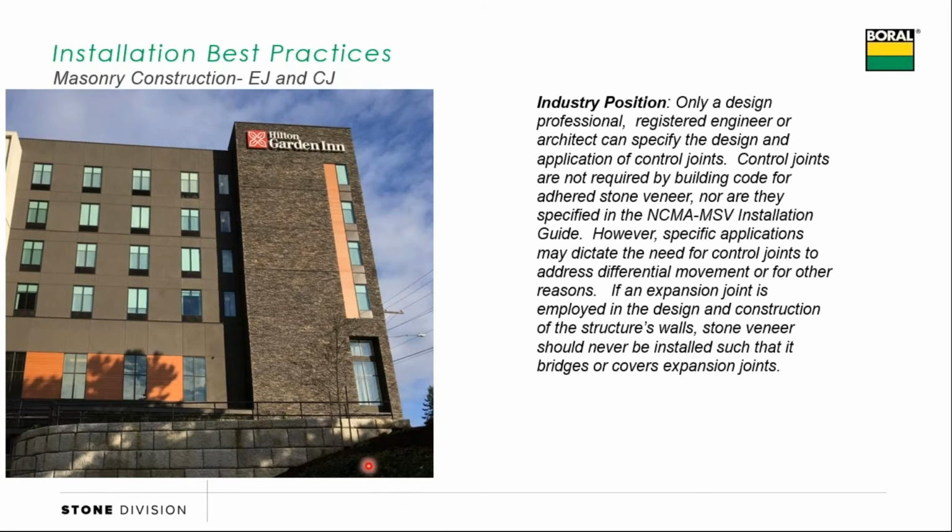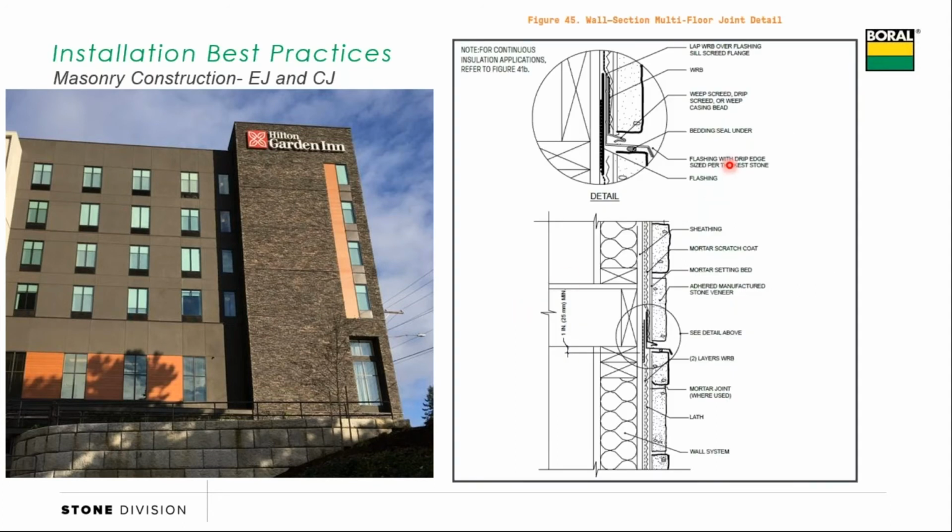And if we haven't put any control joints in, we may begin to see some hairline cracking or buckling in the stone. And so it may make sense every floor or every other floor to put some type of a control joint in. Now, we've got a detail on how that could be done if they want to, but we would recommend the designer or architect of the building decide where those go. I wouldn't make that choice as the contractor. I would ask that question back to the designer.